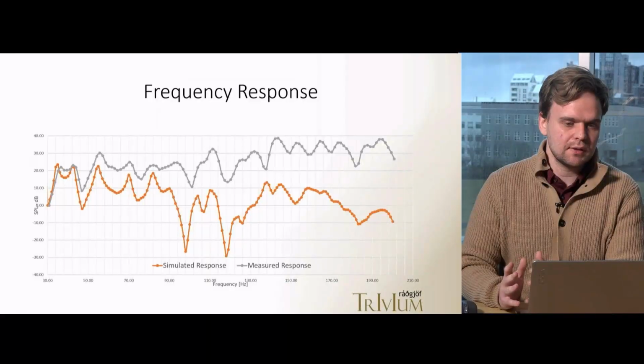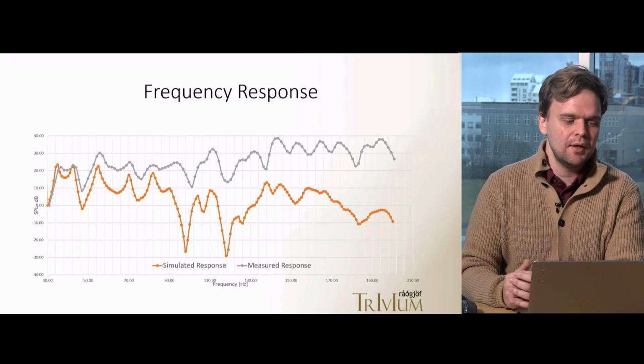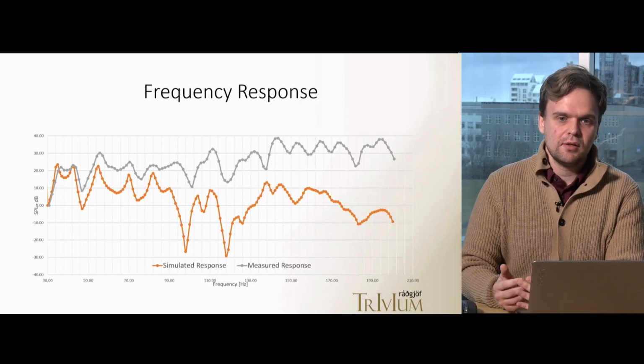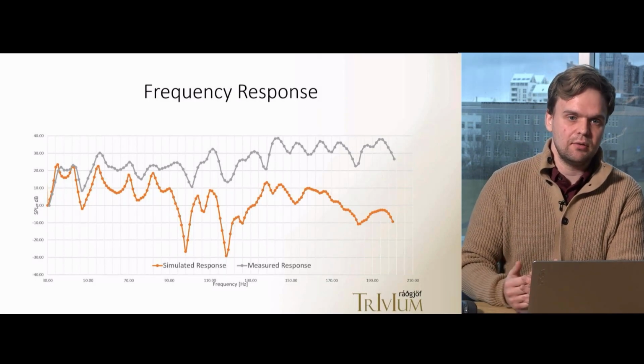That means, for example, that the third mode you can see here is actually a tangential mode. If I had to design this based on my intuition, I would assume that tangential modes would contain less energy than axial modes. But in this case, we can see that this mode is quite dominant. So you have to make sure you treat that very carefully. This is something you would not be able to predict in the same manner unless you do measurements at the end.